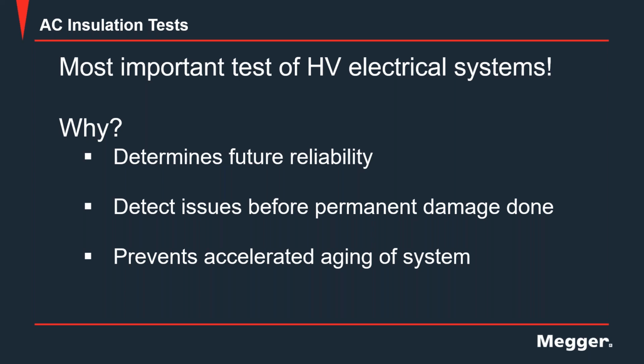I want to emphasize this. We want to be proactive, not reactive. When it's done, it's done. If it exploded in the field, if you had an explosion and it's broken, it's damaged, that's it. It's a catastrophic failure that might have affected not only the bushing but also your transformer and maybe some systems and equipment that are in the neighborhood of these bushings.